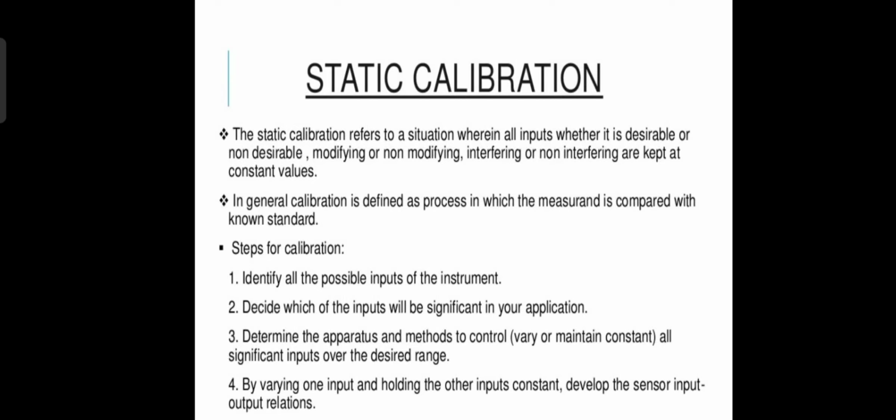The second type is data system calibration. For making valid engineering measurements, the most important consideration is how the transducer operates in the actual test environment with the entire signal conditioning equipment attached. Although not always feasible, the transducer should be calibrated while connected to the same signal conditioning equipment in the laboratory as it will be used on the actual test article. This type of calibration stimulates the desired measurement rather than physically stimulating the transducer's sensing device.